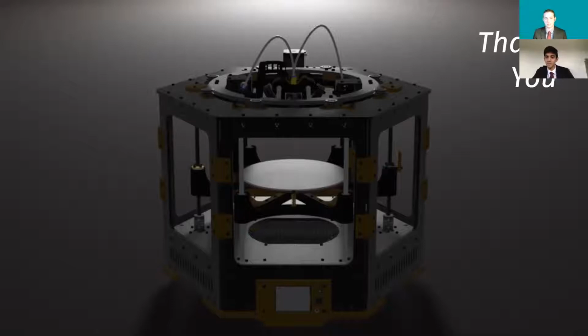Yeah, so one of the main things, and one of the things that I'm most excited about, is that we're working on developing an actual production unit for the printer. The main current design is an acrylic frame. It has a lot of 3D printed parts, and while those are really good for testing, they wouldn't necessarily be good in an industry environment. So some of the things that we are changing are we are redoing the entire frame with a sheet metal frame that should hopefully increase the longevity as well as rigidity of the printer.